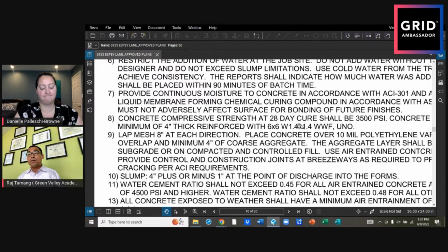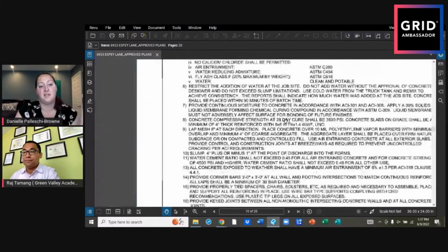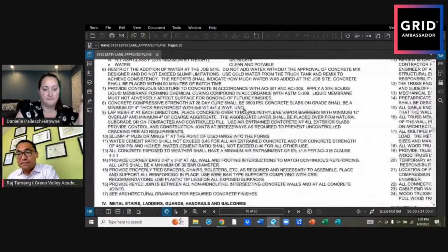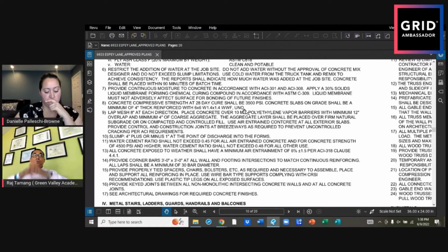So even though your concrete has not gained that 100% capacity, you can continue the work because you are not applying that load. Does that make sense? Yeah, because it doesn't have the weight on it yet. So it's before what they're anticipating it's going to hold. Yeah, it needs to be fully cured to hold the whole entire structure, but you are just starting foundations. As long as they are good for a few days, you can continue the work.